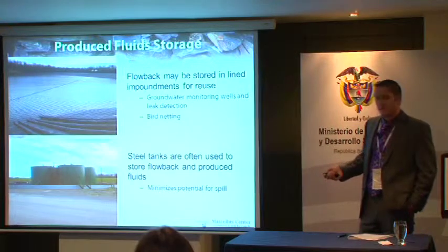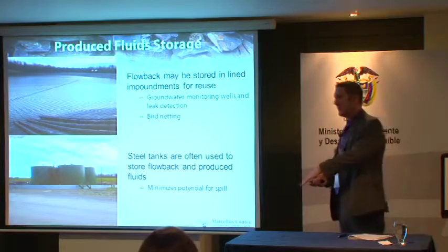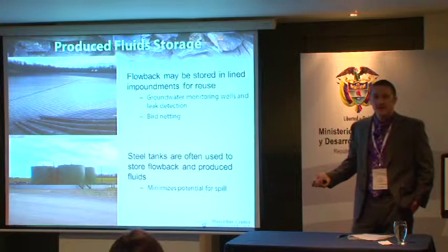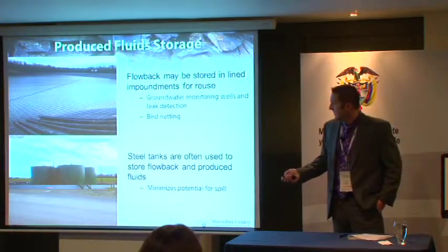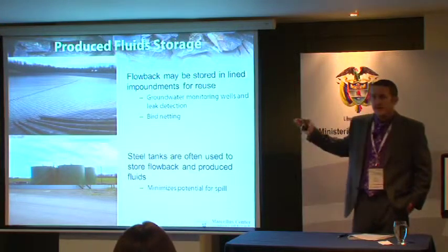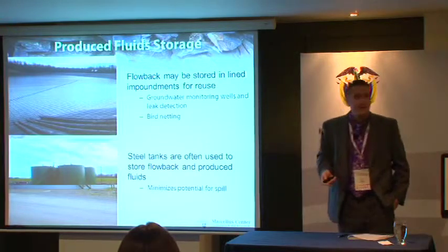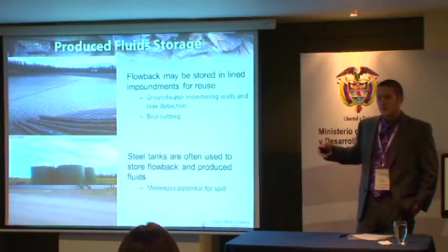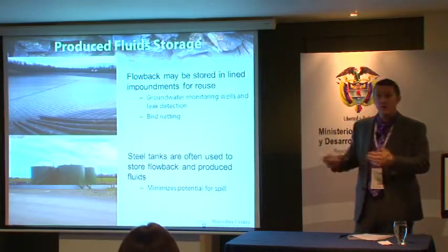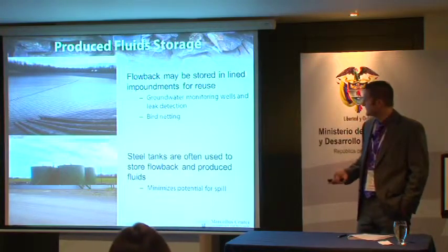But then ultimately, once the wells are put into production, as the volume of fluids being produced from these wells drops off, you'll see these produced water tanks at the well pad, and then they'll again have secondary containment around them. And then these tanks would be emptied on a periodic basis as they fill up, and that fluid would be taken to a treatment plant or be taken perhaps to another well where it can be recycled for hydraulic fracturing purposes.